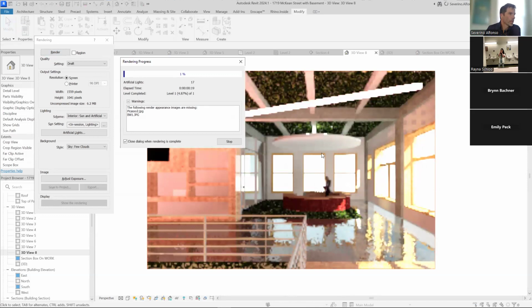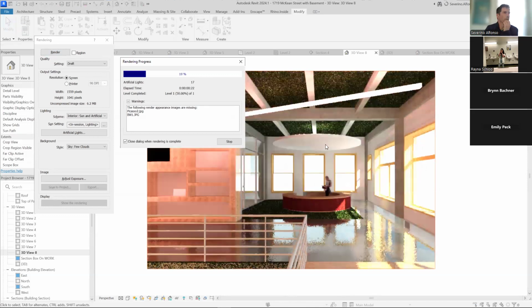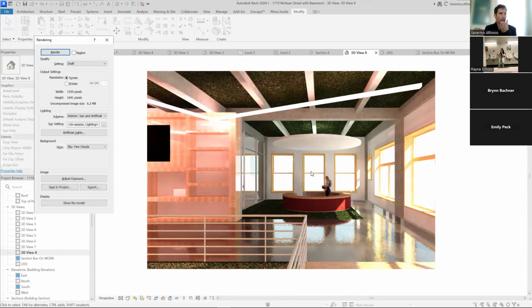So there is. You don't see a light, but it's a recessed lighting behind the ceiling looking upwards. Okay, so you can do that with any shape. If you have a ceiling that ends up in a corner detail, you can just step back the ceiling component and add a little object hiding behind the ceiling, and you can do that type of approach.